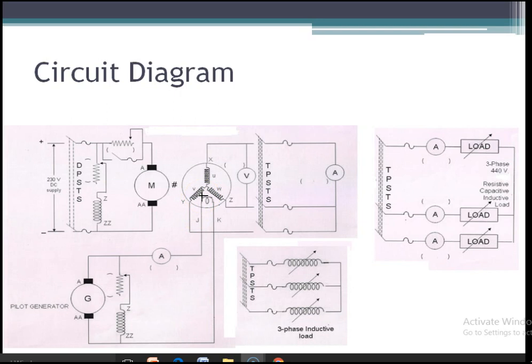In each and every stage you see that there is an increase in field current, and similarly there will be an increase in the induced EMF. This procedure you have to continue until the alternator is able to develop the rated voltage specified by the vendor. This you call the open circuit test.